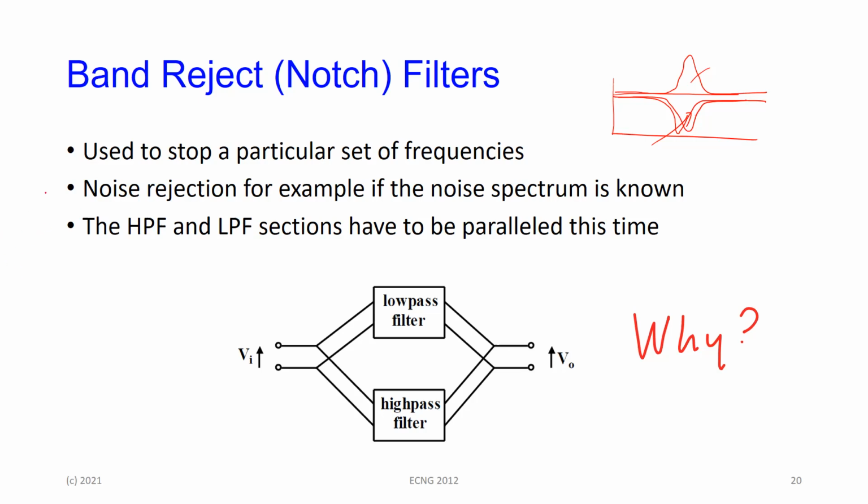So instead of seeing the signal, what you want, looking like that, the signal tends to look like this. The signal is riding a 60 hertz or 50 hertz power supply signal that you pick up because your body is picking up the electromagnetic radiation from the wiring in the wall and so on.